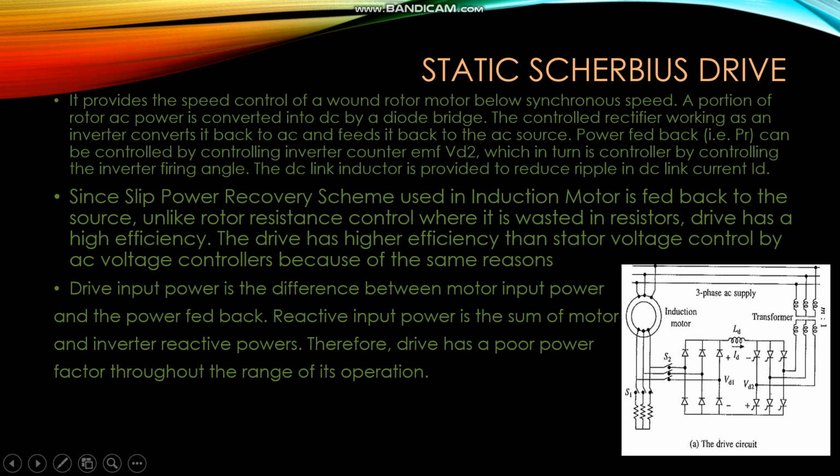Here the thyristor works like a line commutated inverter, and it feeds the kinetic energy back to the source through this transformer. This is the working of the static Scherbius drive. This type of recovery is slip recovery. It is called a static drive because, in addition to the motor, there is no rotating item.